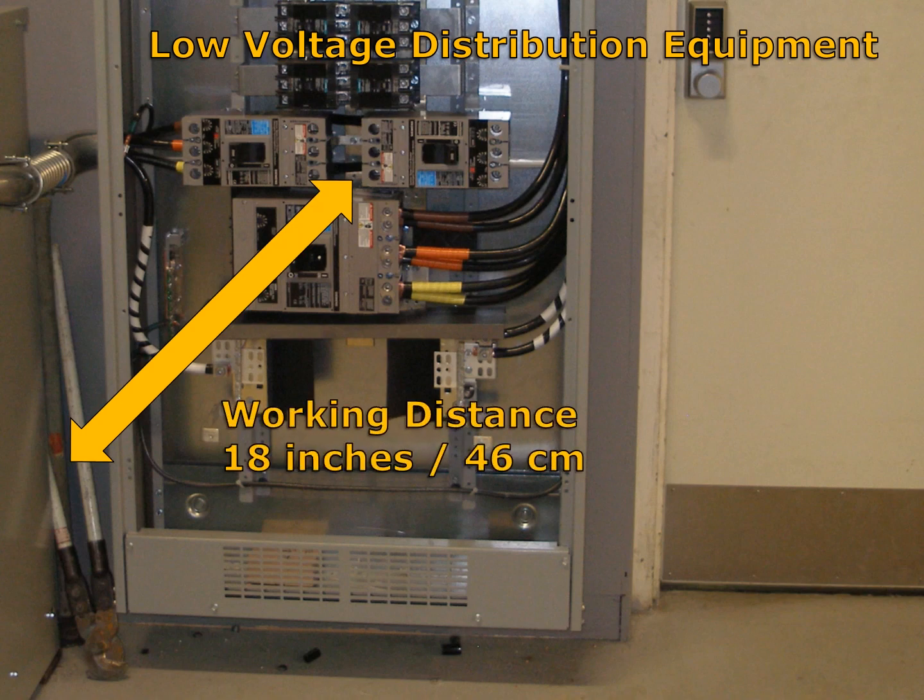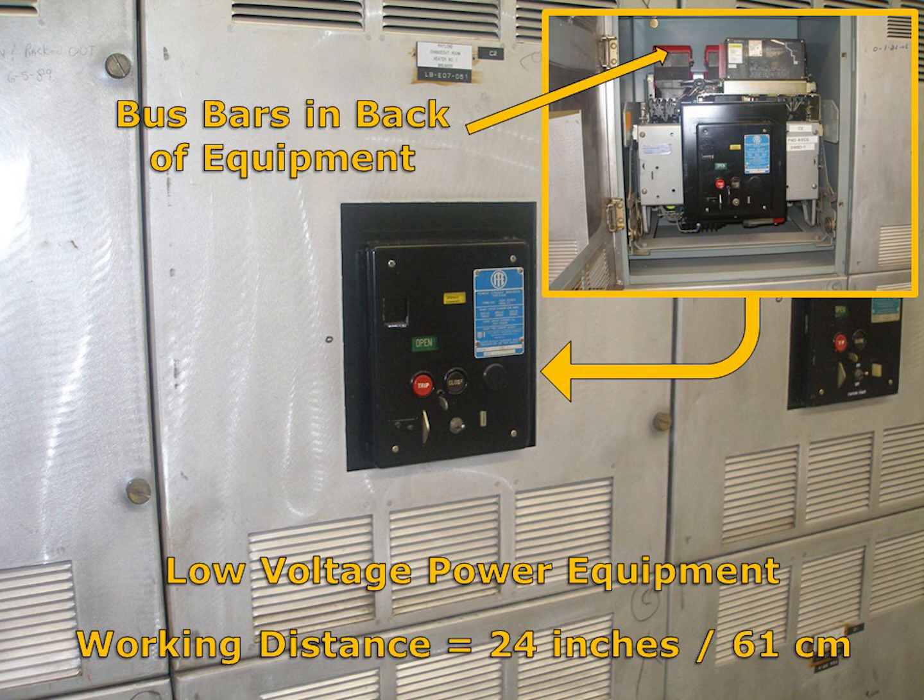That's 18 inches from the source of the arc flash to a person's head and torso or chest. For low voltage power equipment, IEEE 1584 references a 24-inch working distance. Part of the rationale is that with low voltage power equipment, for example switchgear, the exposed energized parts are considered to be a little further back in the equipment.